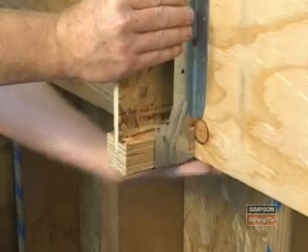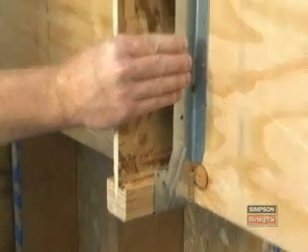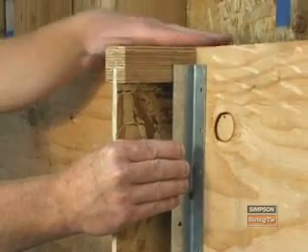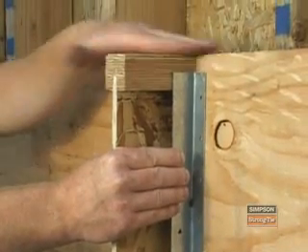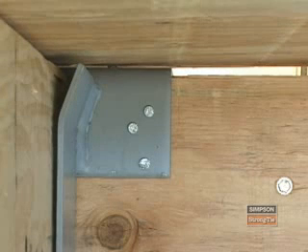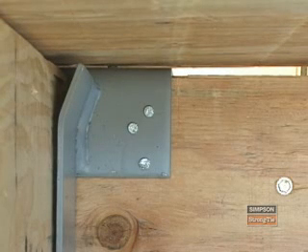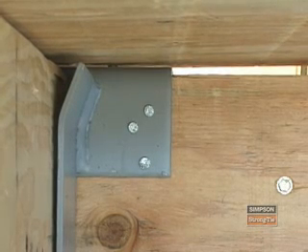But the top flanges are also a disadvantage, because the position on the face of the header is determined by the top flanges. The height of the hanger and the height of the joist have to match to ensure a flush floor or ceiling. In contrast to a top flange hanger, you can adjust the hanger position on a header when using a face mount hanger. Another disadvantage of the top flanges is that they may create bumps in a subfloor.